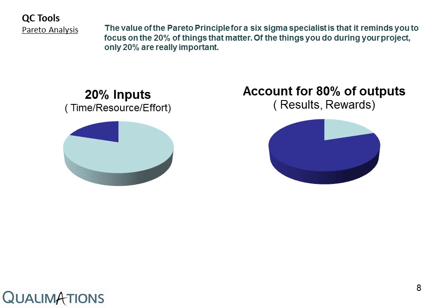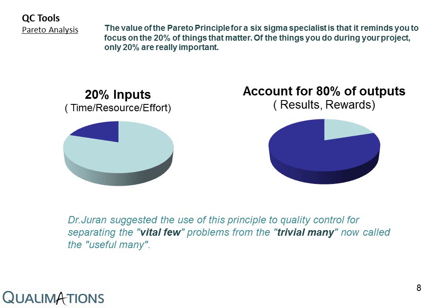Pareto diagram is a tool that arranges items in the order of the magnitude of their contribution, thereby identifying a few items exerting maximum influence. This tool is used in SPC and quality improvement for prioritizing projects for improvement, such as prioritizing setting up of corrective action teams to solve problems or identifying products on which most complaints are received.